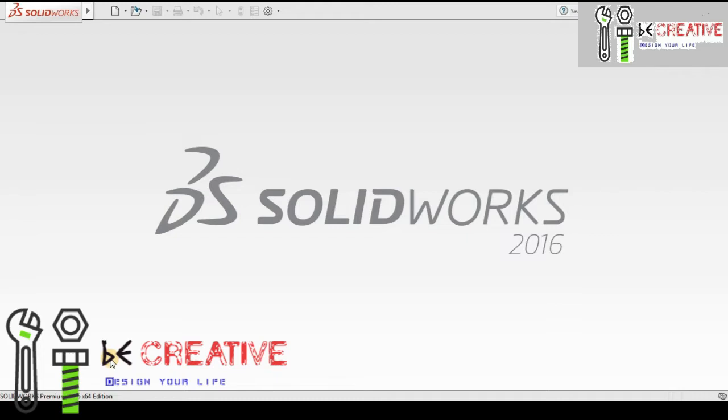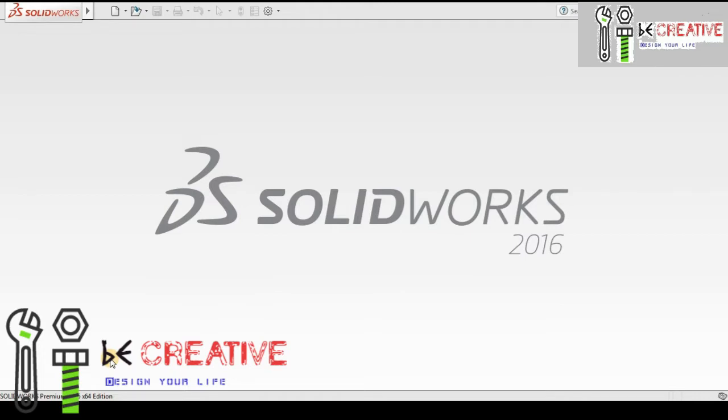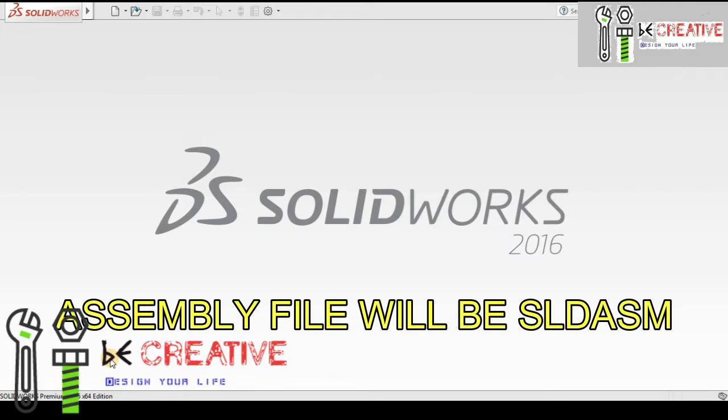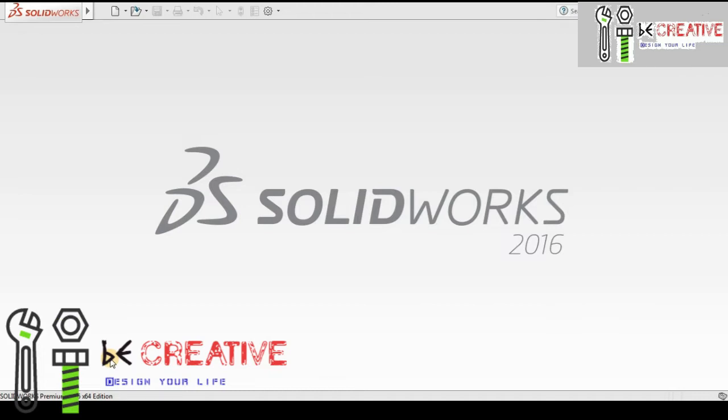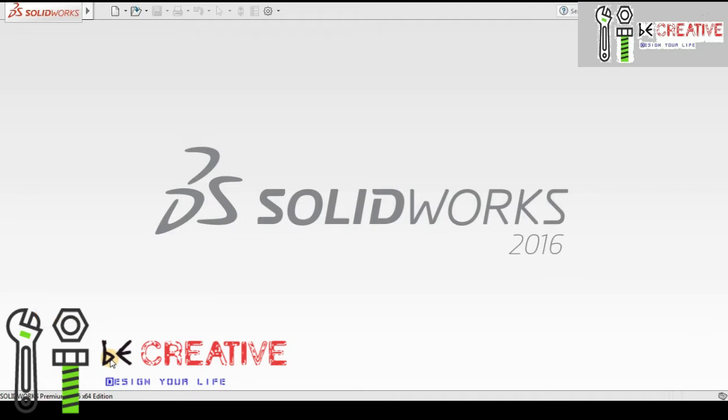In this video, we are going to learn about what are the different versions of SolidWorks. For the part file, it should be in SLDPRT format. Assembly file format will be SLDASM format. Drafting or drawing file format will be SLDDRW format. These are the different versions of SolidWorks.